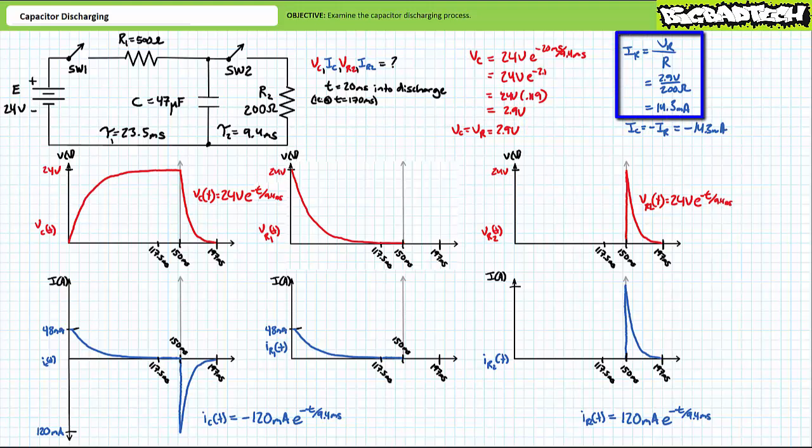When roughly 2.9 volts is applied across a 200 ohm resistor, Ohm's law demonstrates that 2.9 volts over 200 ohms, or roughly 14.3 milliamperes of current, will be traveling through it. Given R2 and the discharging capacitor are in series with one another, this implies that 14.3 milliamperes is traveling out of the capacitor, where the negative sign implies a reversal of current flow during the discharge phase.